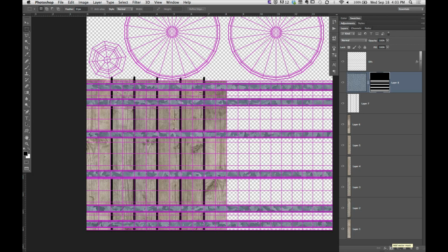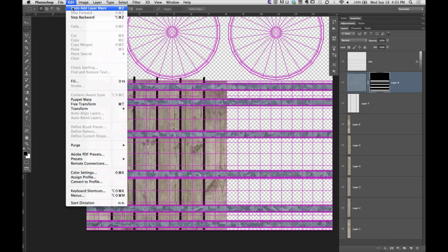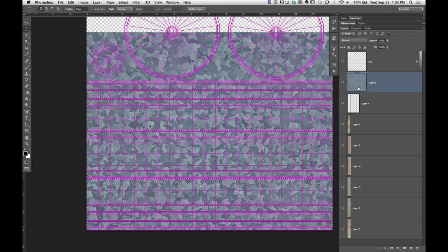Yeah, so I had the areas of my UV map that represented the metal bands selected. And I just used the marquee selection tool to do that. Okay? In my layers palette, let me just hit undo real fast and reverse for a second. In my layers palette, I had the photograph of the metal texture selected. And then at the bottom of my layers palette, here's the magic. Here's the magic, Austin. It's that button right there. The Add Layer Mask button.